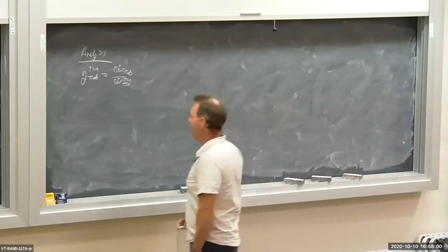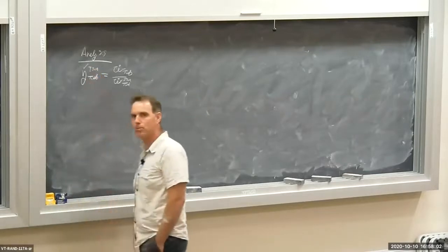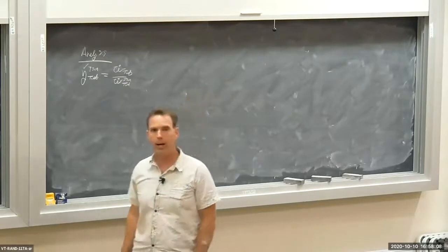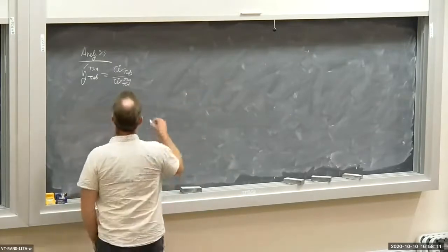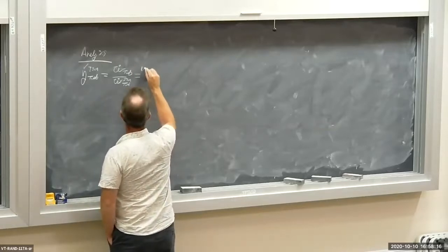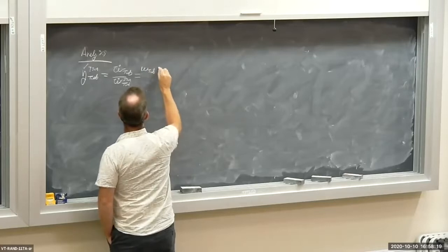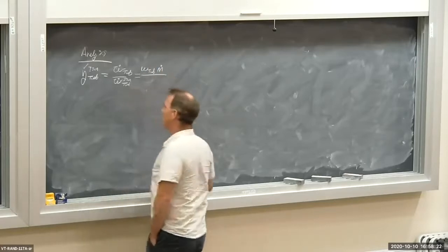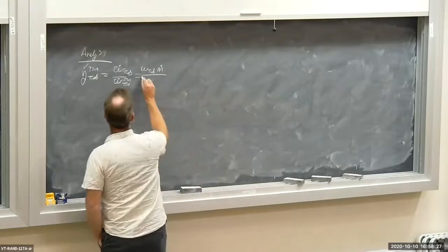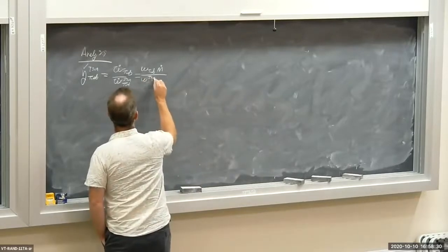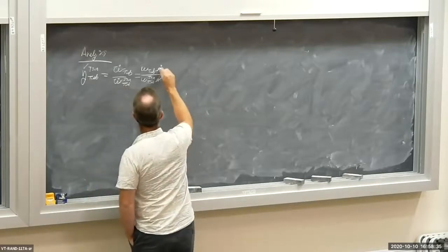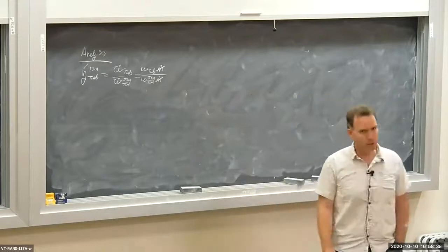Now, I have the isentropic turbine efficiency as 86%. And I don't want W dot turbine, I want the specific work. Well, I guess we need to massage this a little bit. So W dot turbine is the specific work of the turbine times m dot for the air going through the turbine, divided by W for the isentropic turbine times m dot. The m dots cancel out. That's the definition of isentropic efficiency.